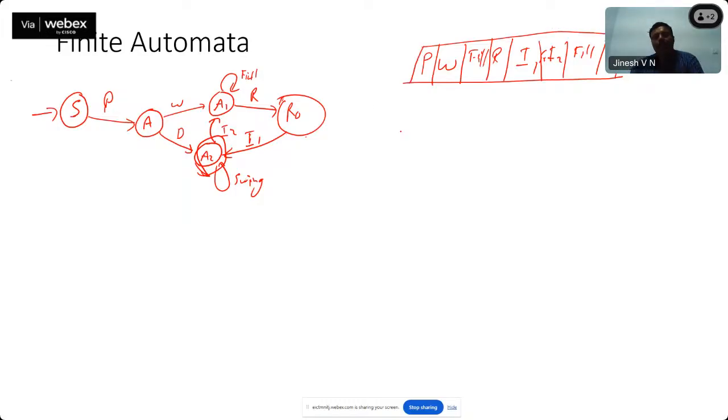Okay, so from where you are reading, your system will start from the power button. So the state, okay, then the power button on is possible only for the state where it is sleeping. So in our design case, sleeping mode is the start state of the machine. So you start reading from S. Then with the S, if you are reading P, what is happening? Your state will change to A. Then on A, if you are reading A, what is happening? Your state will change to A1.